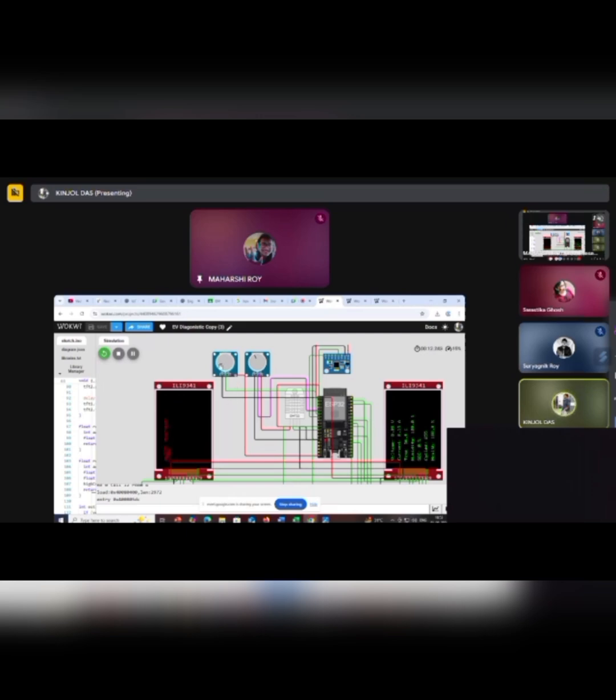So, whenever we change the potentiometer, the battery voltage increases. That means the charging starts. As on the right side, you can see the charging starts at 5.2 volts. So it will detect as a low voltage. Below 12.5 is low voltage. So when the battery starts charging, it continues to go up, and at a time